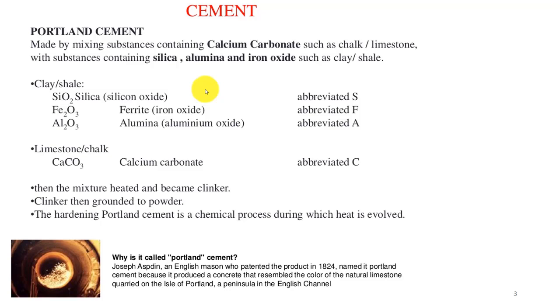So the calcareous and argillaceous rocks, when mixed and heated, become the clinker. The formation of clinker requires a large amount of energy.